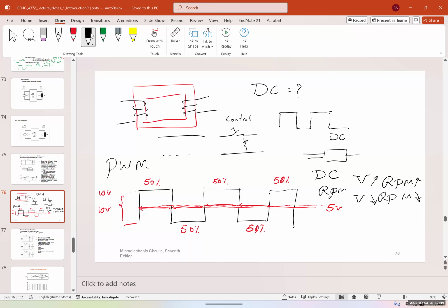The only problem with a battery is that it takes time to charge and discharge. I need something to quickly charge and discharge. Yes, I can use a capacitor or an inductor. What a capacitor does is it charges and then it discharges. So you're going to have something like this, charge and discharge, and if you have a large enough capacitor, same thing that you had in a rectifier. Do you remember what you had in a rectifier in electronics? Yes? You would connect it to a capacitor. So you can use a capacitor to take the average of this, okay?